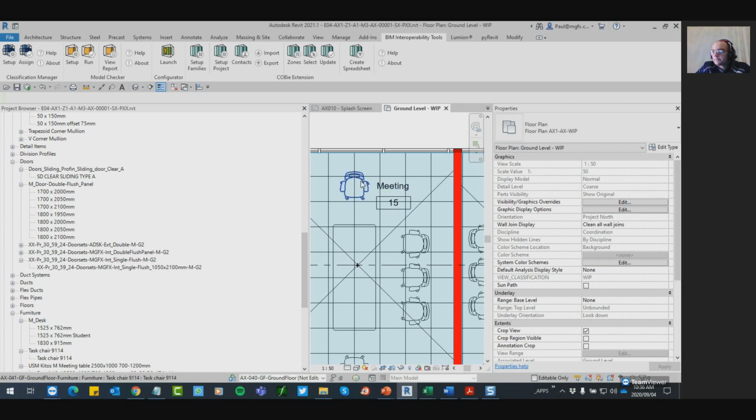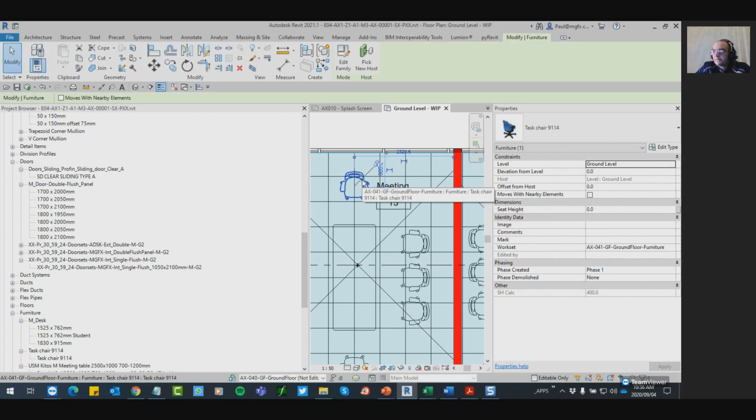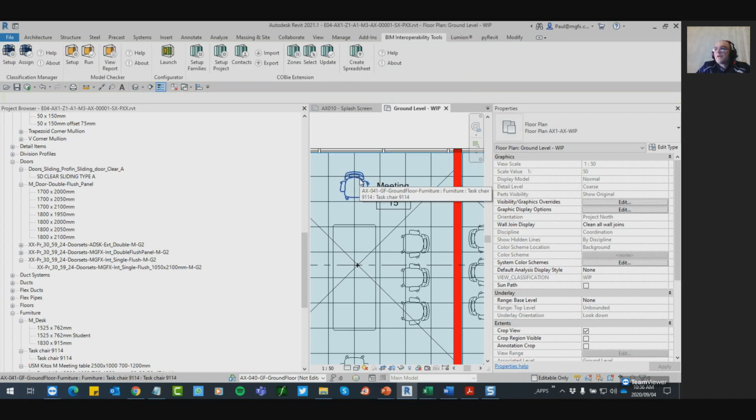For each project, you would have to do this repeatedly for each and every project, because you can't just go and write the family. If I had to open this family, remember that the family is within the project. The information that I've applied to the family exists only within the project. It's not in the original chair family file. So the information is not stored in the library. It's not part of the information that the check came out with.